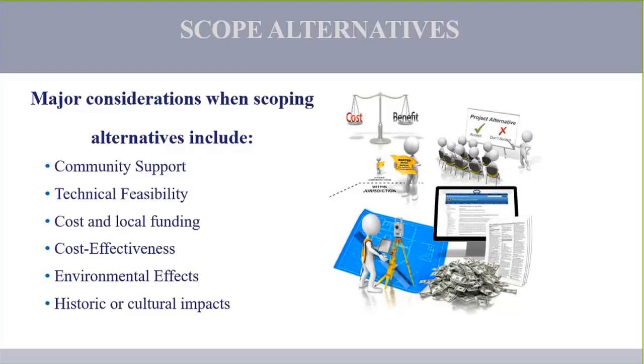Your environmental impacts. Are you going to be impacting the environment very detrimentally? Are you going to be imposing any risk? Would it pass EHP? Historic or cultural impacts. Does that area have maybe ancestral burial grounds that might have some big EHP issues if you start going through, because an archaeological survey would need to be conducted. So really think about all those types of ideas during this process.